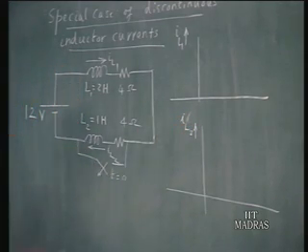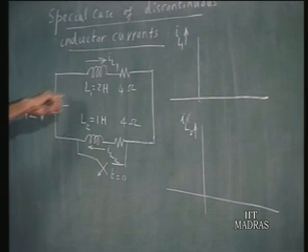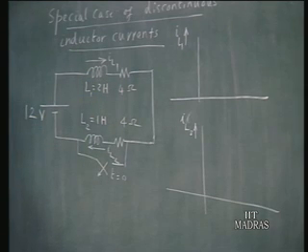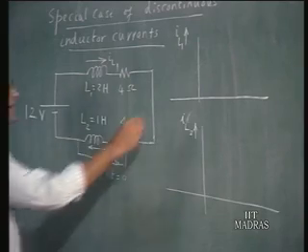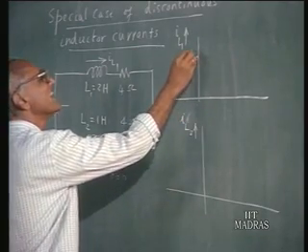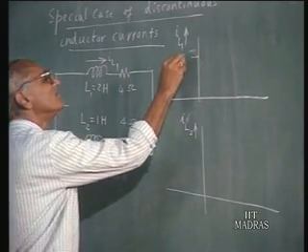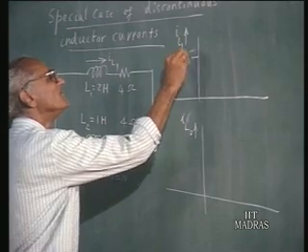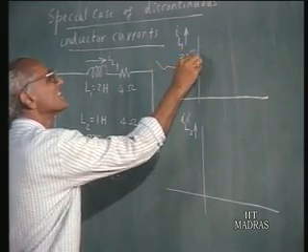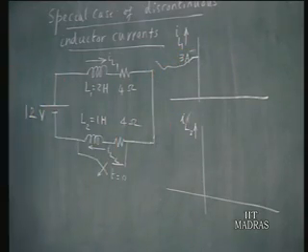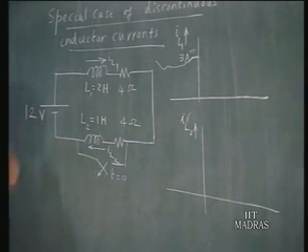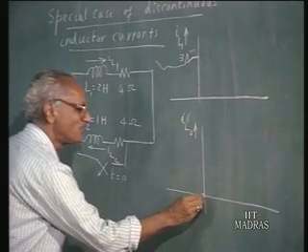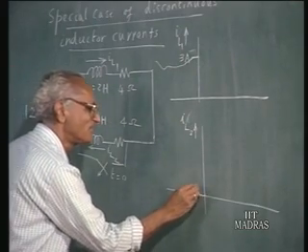Now, when the switch is closed, 12 volts drives a current through the 4 ohm resistor, therefore, there is 3 ampere current because this is a short circuit, and therefore, at t equals 0 minus, this current is 3 amperes. As far as IL2 is concerned, because this is shorted, the current passes through the shorted switch avoiding this L2, therefore, it is 0.